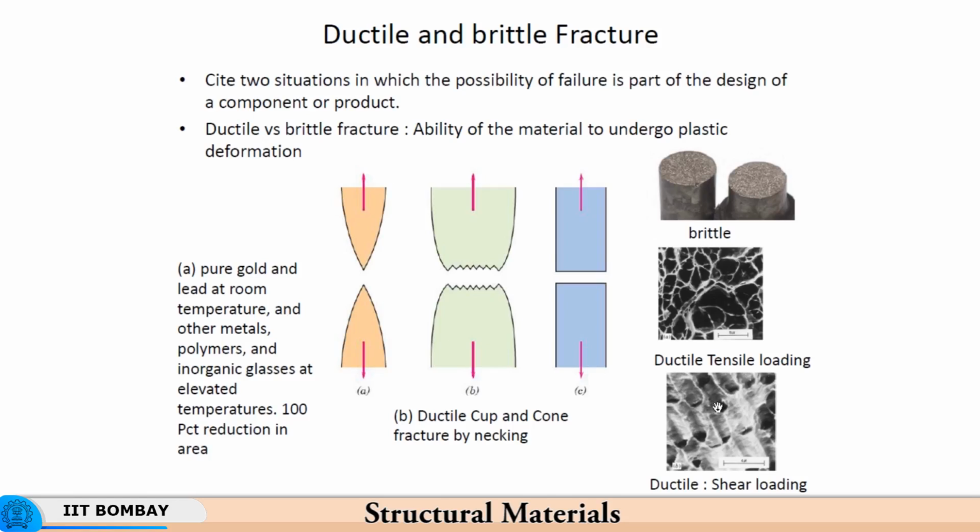So, now the load carrying capacity is getting depleted on a microscopic scale. On a macroscopic scale, you will find that the load carrying capacity is good, it is adequate because the material is work hardening. So, these are the ligaments which would be work hardening during deformation, but then as they grow thinner and thinner, they would fail, and because of the failure of the ligaments, you will have coalescence of voids, and voids per se do not have any load carrying capability. So, the cross section of the material that carries load will continue to get depleted because of the growth of these voids, and then there will be a point at which the cross section just does not have enough strength to carry the load, in which case there will be